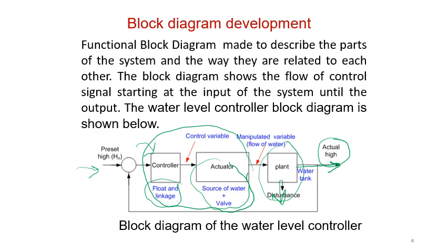Notice that the controller with the actuator is considered as a controller, both of them. They are the float and the arm with the valve. Then the whole tank is the plant, and the feedback signal is coming from the output here, going to the comparator, where the comparator actually is again the float with the arm. Both of them are comparing with the valve. They are comparing and taking a decision, and the decision will be either to open or not to open the inlet.